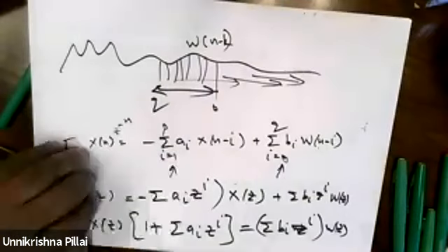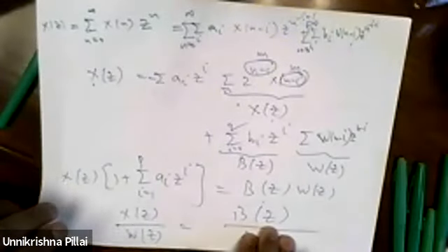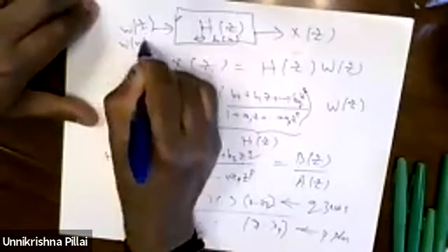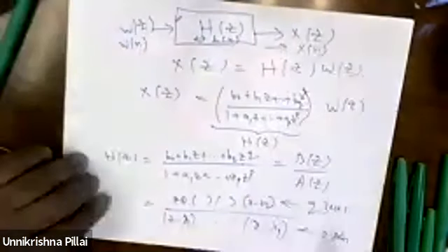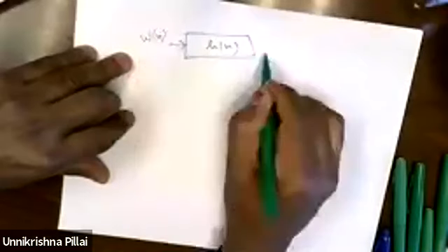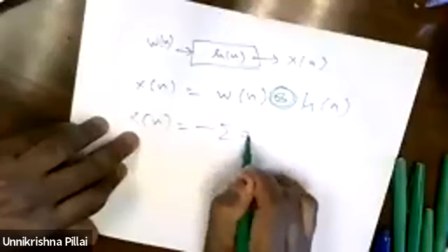Now, if you take a transform of that into the Z domain, you get this picture. So, to answer your question, this relation can be written like this, but in time domain, you have an inverse transform h(n). Here you have w(n), here you have x(n). Of course, you are right. So x(n) will be, if that's what you are asking, here you have h(n), here you have w(n), here you have x(n). Remember, you can certainly write it like this. The output is w(n) convolved with h(n), if that's what you are asking for. You can write it like that. But we know that what we started with is this model, that I don't want to lose the model.